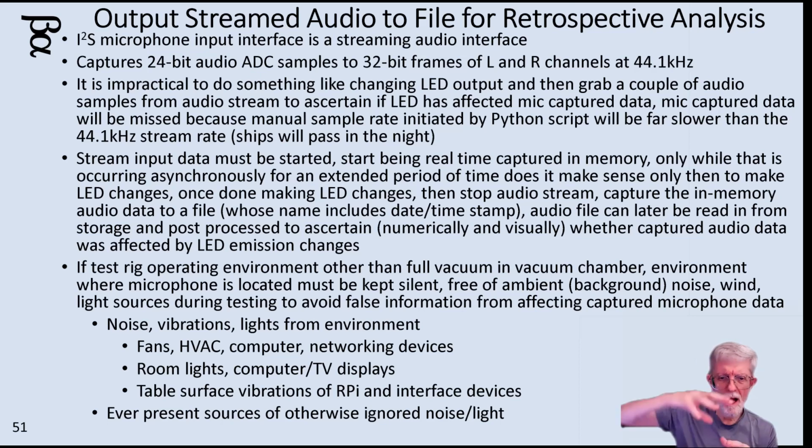You record the log of you making the changes. You record the waveform to a wave file. And then you can play the wave file back and look at where the peaks and valleys are, and then know the timestamp. When you started recording, you got a timestamp. You know the speed of the recording, so you know where all the edges of everything are, and you know from your log file where the timestamps are. So that's how you judge, was it me or was it Memorex?